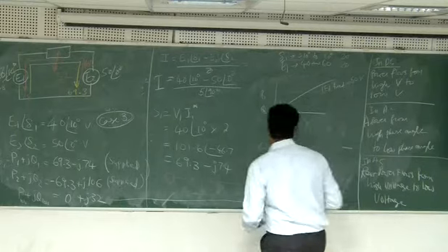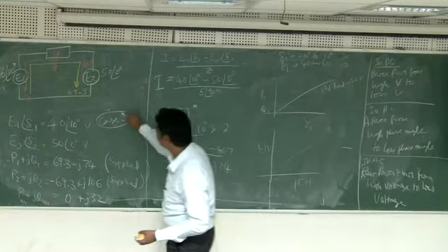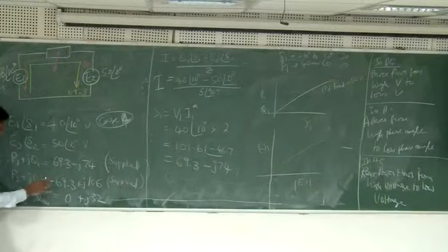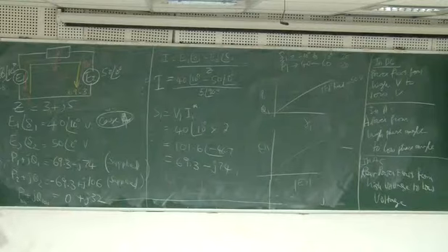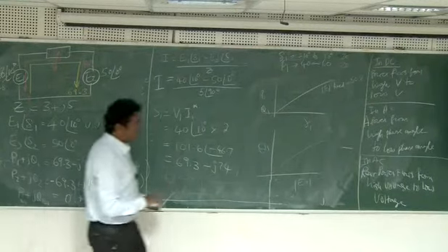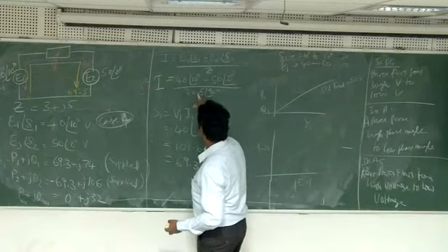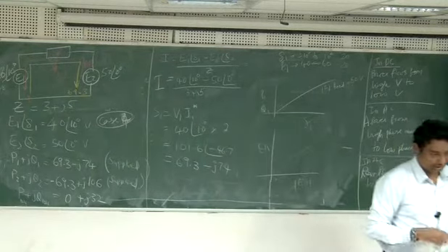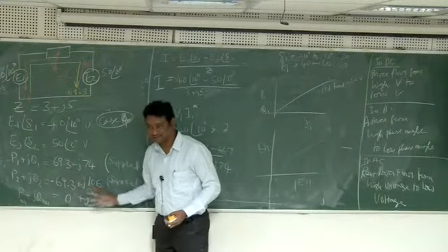So quickly, can you imagine what happens now if there is a resistance? If you look at case 4, the whole problem is the same. I think these two are the same, and just that Z will now be 3 plus j5. So there is going to be some power loss also. Okay. So we can calculate it, we can do all these things here, but here it will be 3 plus j5. If we repeat the same problem, you can verify the power sharing, how much is the loss, and all these things.